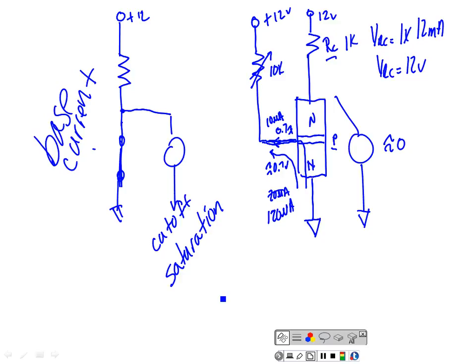So cutoff, it acts like an open switch, right? All the voltage would be dropped across the transistor, right? You understand, because it's acting like an open switch. And that happens if we get that base below 0.7 of a volt, or approximately 0.7 of a volt. You know that when you did your diode curve, it came over here and started conducting around 0.6. But if I'm down in here, we say it acts like an open switch. Now, it's not an open switch. Y'all understand that? I might measure a little bit of voltage across my transistor, but it's not going to be enough that most meters that we have would measure.